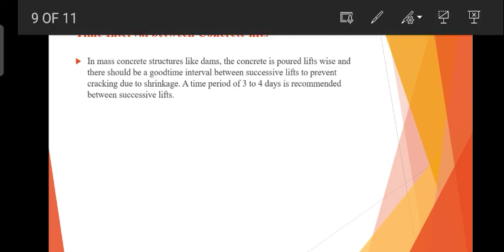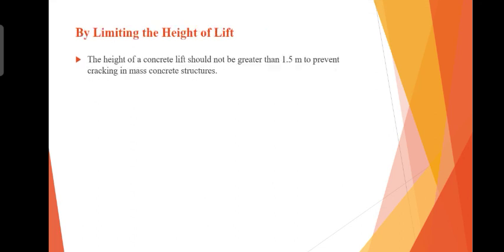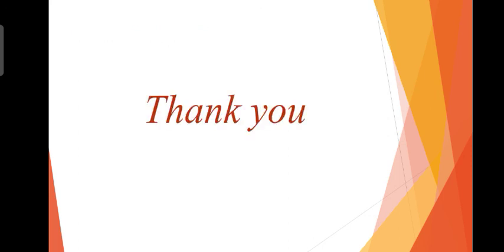Then the next one is limiting the height of lift. The height of a concrete lift should not be greater than 1.5 meters, to prevent cracking in mass concrete. Thank you.